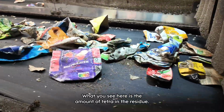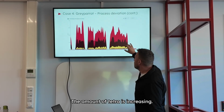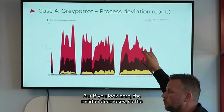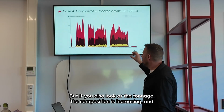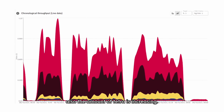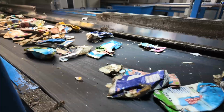What you see here is the amount of tetra in the residue. The amount of tetra is increasing. But if you see here, the residue decreases. So the composition will also change. If you also look at the tonnage, the composition is changing, but the amount of tetra is also increasing. So then you know there is a problem in the tetra line.